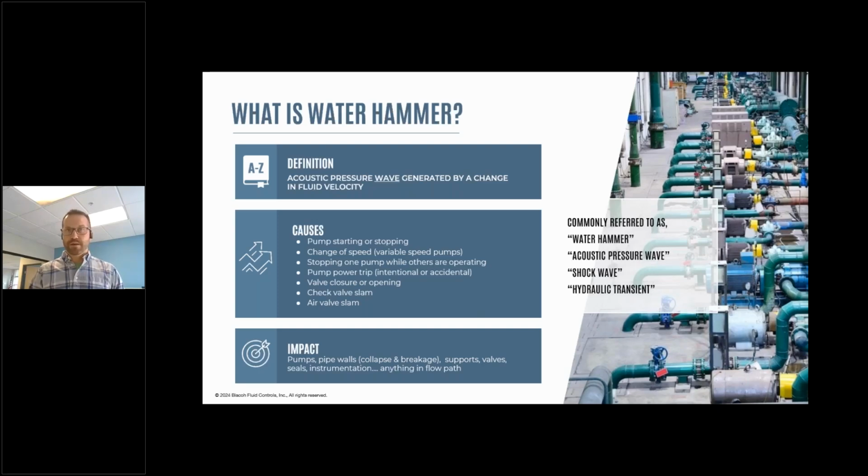You've probably noticed it when you're filling up your car at the gas station and the pump shuts off automatically because the tank is almost full, or you're putting a little bit more in, and you see the hose shaking a little bit as you're doing that. This is a WaterHammer event that's going on inside of a gasoline system, right? Because we're changing the fluid from moving through the hose into the tank of the car, and we're stopping it. When we open that line again and put more fluid in, we're changing the velocity again. We're getting a new transient event.